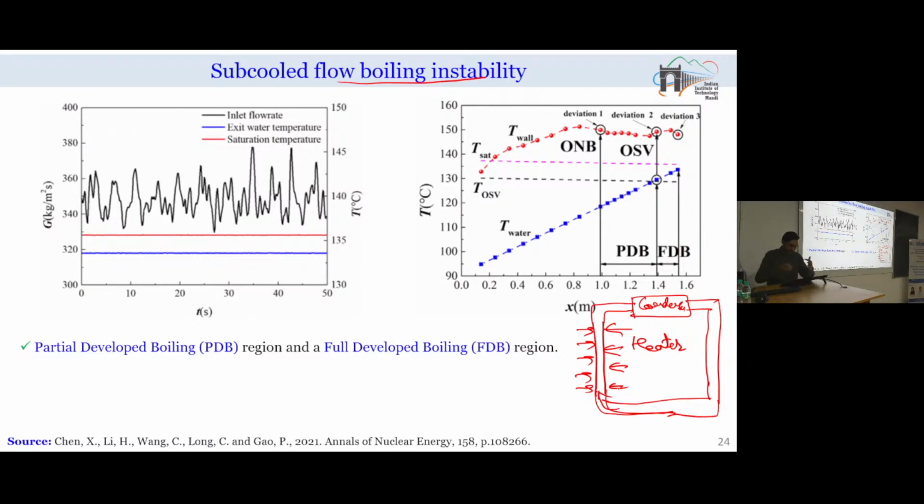Of course, in the actual arrangement above the heater section, we need to keep a large height riser section so that we can actually achieve the necessary head. So, now when we will be heating the working fluid in this heater, what will happen? This working fluid, because of the decrease in its density, will be rising in the upward direction, and from here it will be falling in the downward direction.